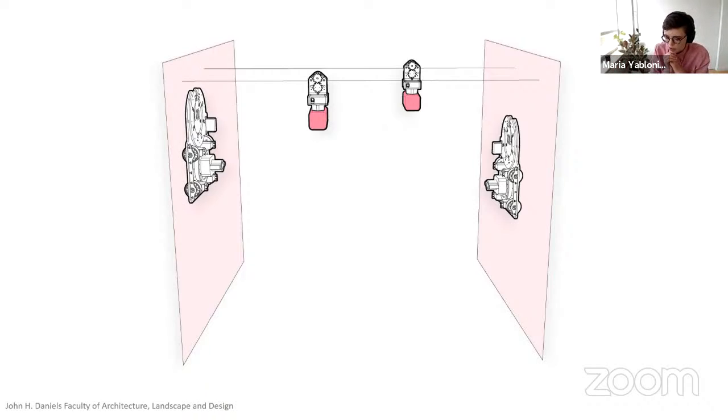The other problem that I was excited to solve was the fact that this vacuum wall climbing robot, because it's based on negative pressure in order to stick to the wall, requires a lot of energy to operate. As you've probably noticed in the videos, every one of the wall climbers is a tethered robot, so it has a cable running to it. Because of that, the workspace is not entirely free. Once you place this curve of anchors, you're inherently constricting the robot from entering inside of that curve, because once you pass in between two different anchors, you're in danger of entangling the cable around the anchor. And then, that's it. You have to come in and manually fix it.